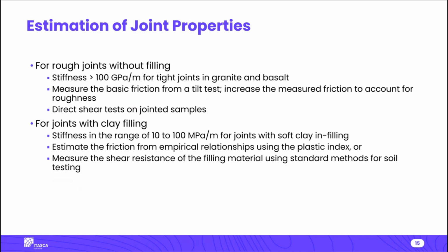Again, this is just some guidelines for ideas about what to choose for stiffness. To some extent, it's not super critical what you choose for the stiffness, because most of the deformation occurs after this thing starts sliding. We expect there to be a very small amount of deformation when it's not sliding. So the stiffness isn't really that critical. But you do want to give a realistic guess here. So this is just some guideline.